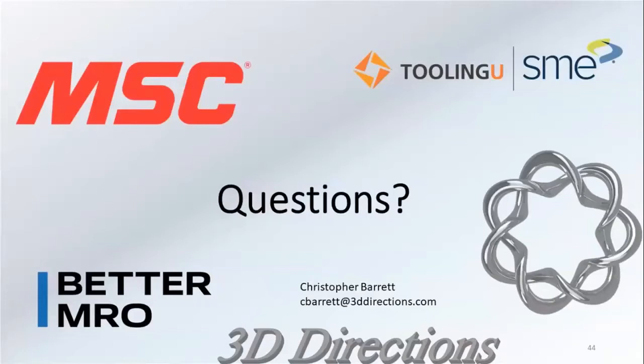The hard part we're having is we're trying to spot lack of fusion defects. Everybody seems to be caught up with identifying those. The regular egregious defects that you would see while you're developing a new build file, you typically can spot those within the first couple of hours, and so we don't set a machine to identify those and let you know. We just assume you'll walk back up and check the machine. They're trying to build a complete package before they release it, is really the bottom line.